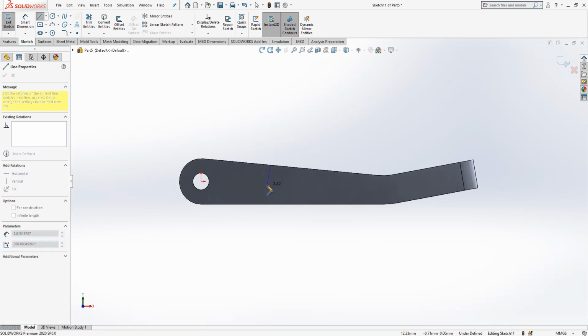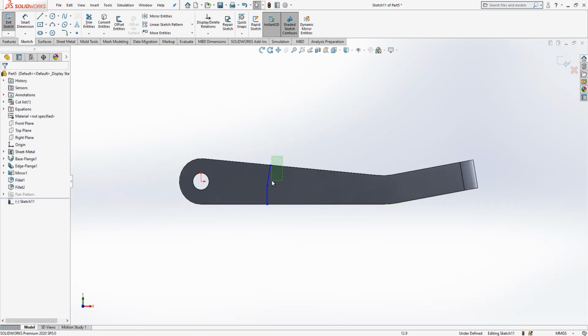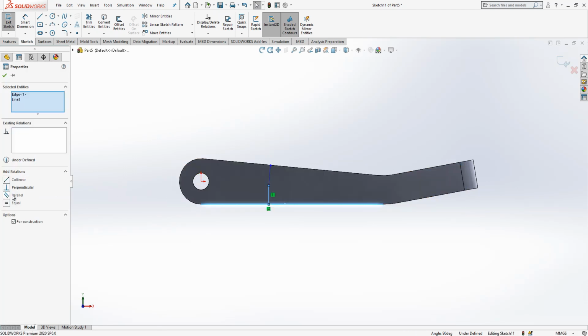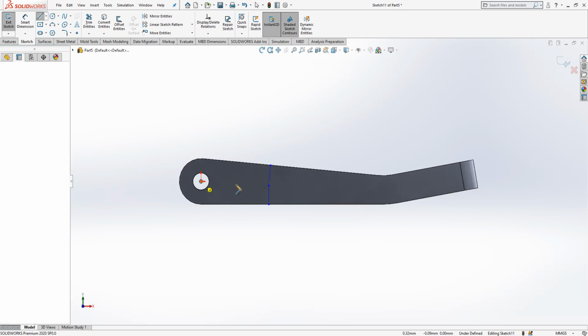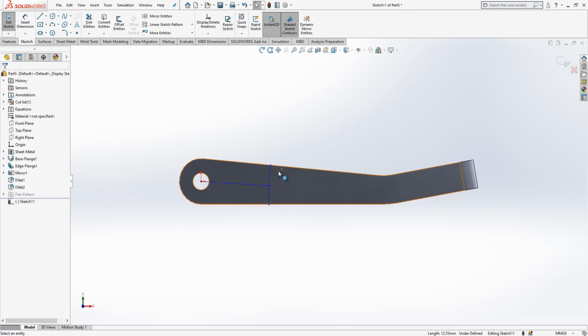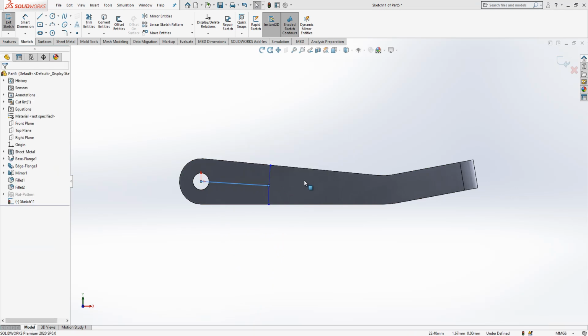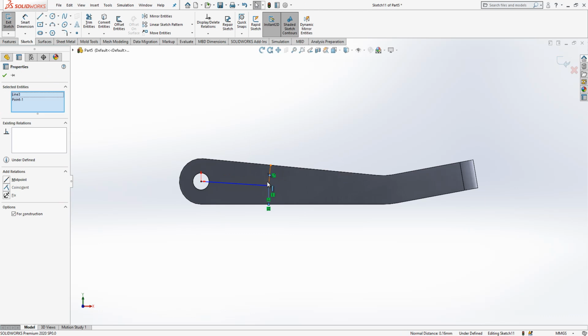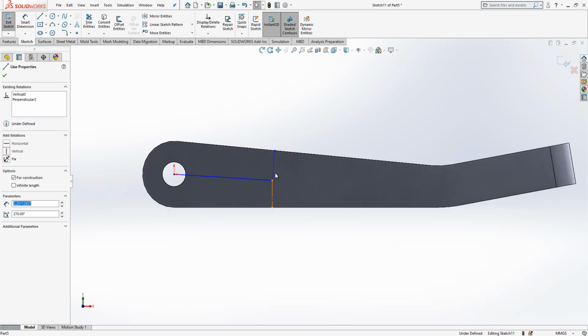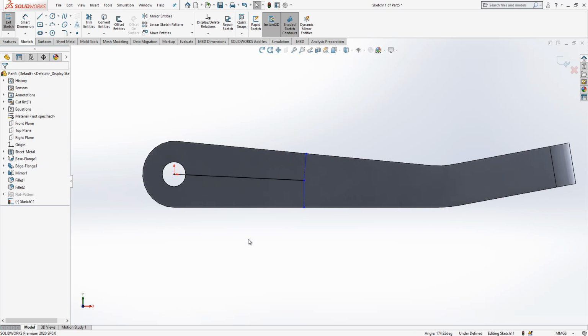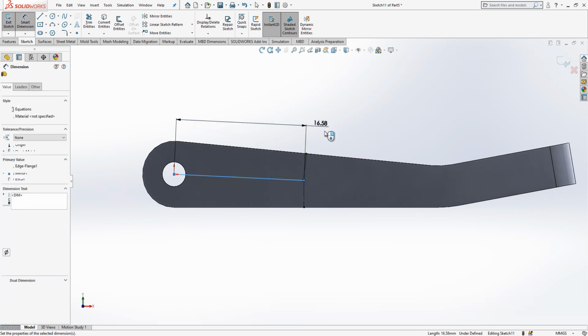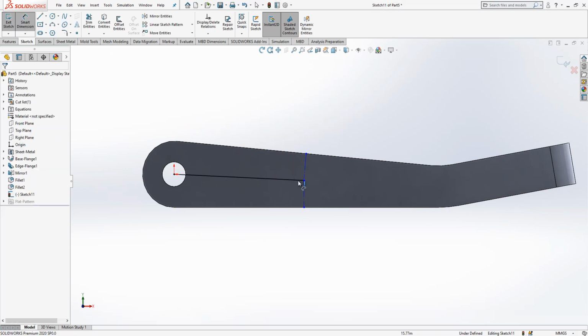something like this. We will make, select two of them, construction geometry, and then now here perpendicular, here perpendicular. Nice. And then from here to here a line. Sorry, we will say they are equal as well. We missed that. So here I have a 12 millimeter distance.